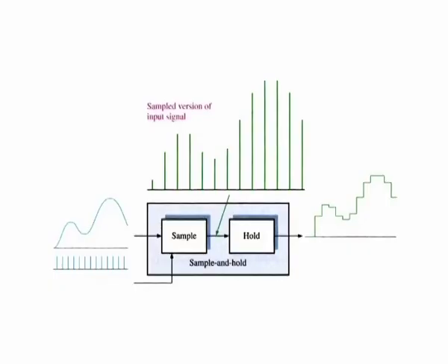On the other hand, if a sound signal is not sampled at a high enough rate, the effect of aliasing will become noticeable with background noise and distortion. The holding operation is part of the sample and hold block shown in the figure.